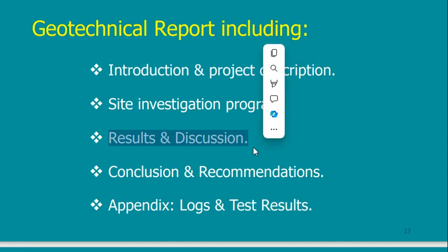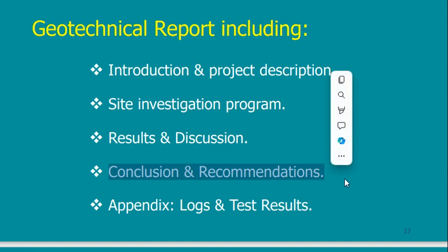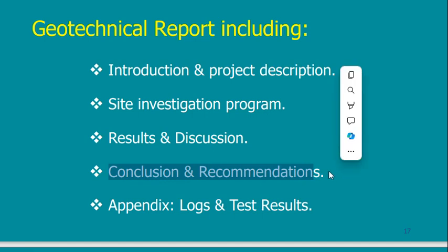Then I have to put the results and the discussion. Now I have done a few tests. Then these tests, I have to put the results and comment on these results. Were they good, bad, do they need my interference or not, something like this. Then finally, I will give people reading this report conclusion and recommendation. Is this site feasible? Do I have to use it or do I have to look for another one? If it is feasible, what are the soil parameters that I will need? What is the strength of the soil? So I put everything. Usually, normal engineers cannot study all of this. They will go directly to the conclusion and recommendation, and they will read it and do whatever you put in this conclusion and recommendation.